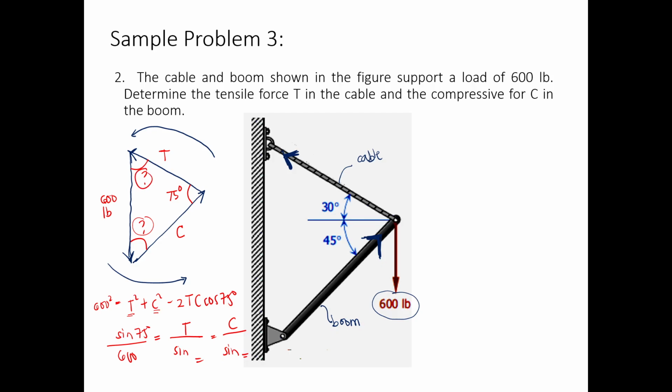So that's the shortcut method, and you only use it if you're really confident in answering the problem right away. But if not, you have to go very basic: summation of forces x equals 0, and summation of forces y equals 0. So, going back to what I showed, I said the force triangle is better, but for this problem it is not better anymore.